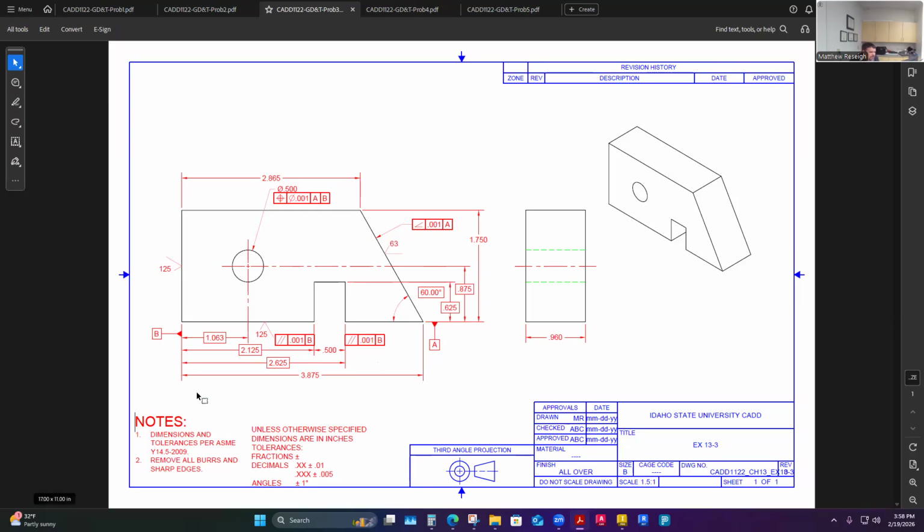Surface finishes, right? It does have some particular surface finishes. Is this a medium fine finish, 63 micro inches, and here it's getting quite fine. So we're requiring some pretty heavy controls over this. Here's another question, because I have this broken surface: do I need to apply the surface finish to both sides to be more correct? When in doubt, it'd probably be better to apply them to both or put 2x.